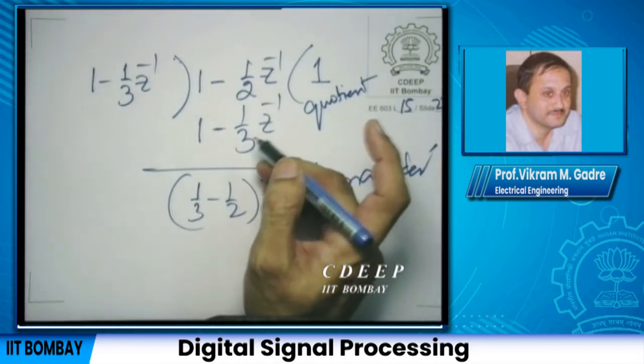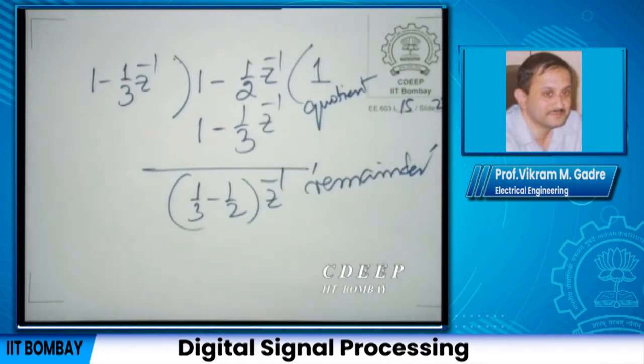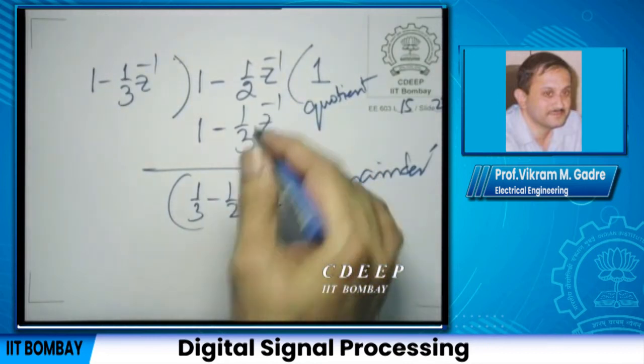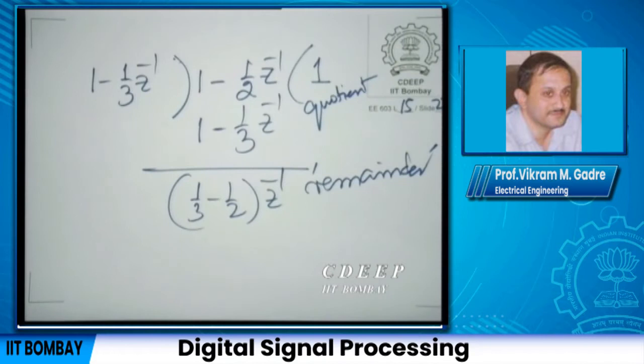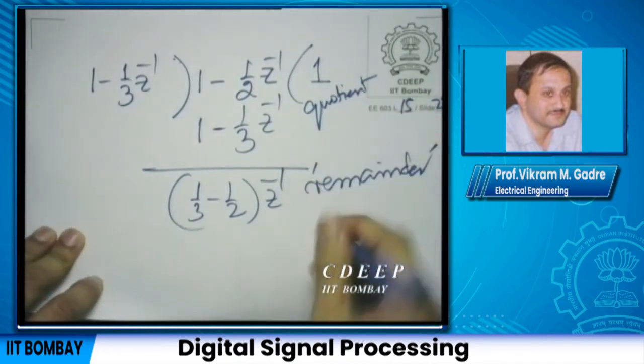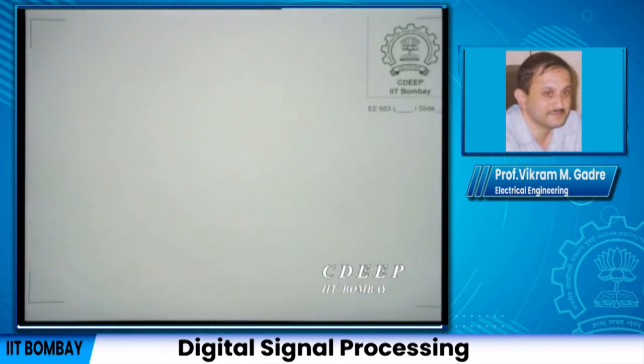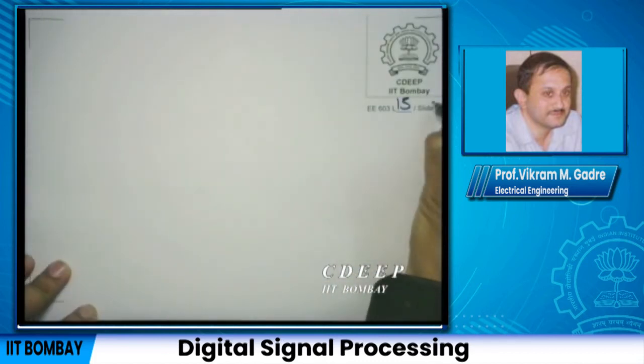Now, here the long division, actually I intentionally did what is not useful. It is not incorrect, but the long division here needs to be done with z inverse as the lead. So, this quotient and remainder will not help us here. In fact, we should do the long division the other way.